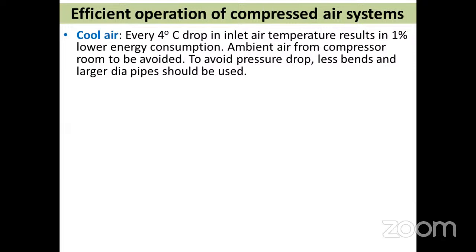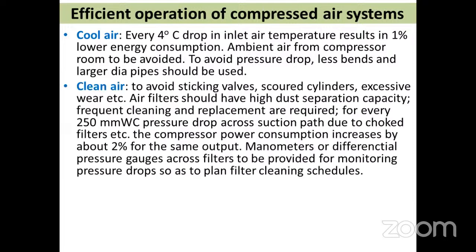So we prefer to draw air from the ambient, that is, from a well ventilated area. To avoid pressure drop, fewer bends and larger area pipes should be used.